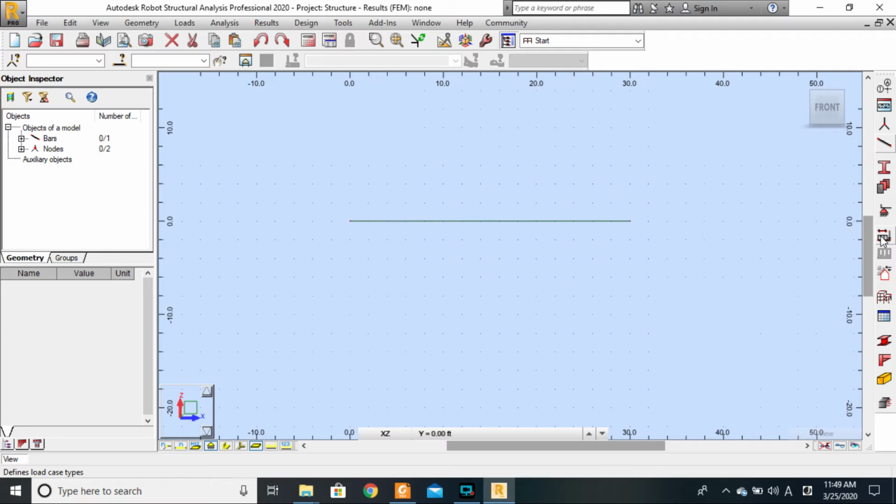You have dead loads, which are loads that are permanent in their position throughout the lifespan of a structure. You have live loads that can vary in magnitude or position throughout the lifespan of the structure. You have wind loads, which is technically a kind of live load also, but has its own specific way of dealing with. You have snow loads and earthquake loads, right? You have different kinds of loads.